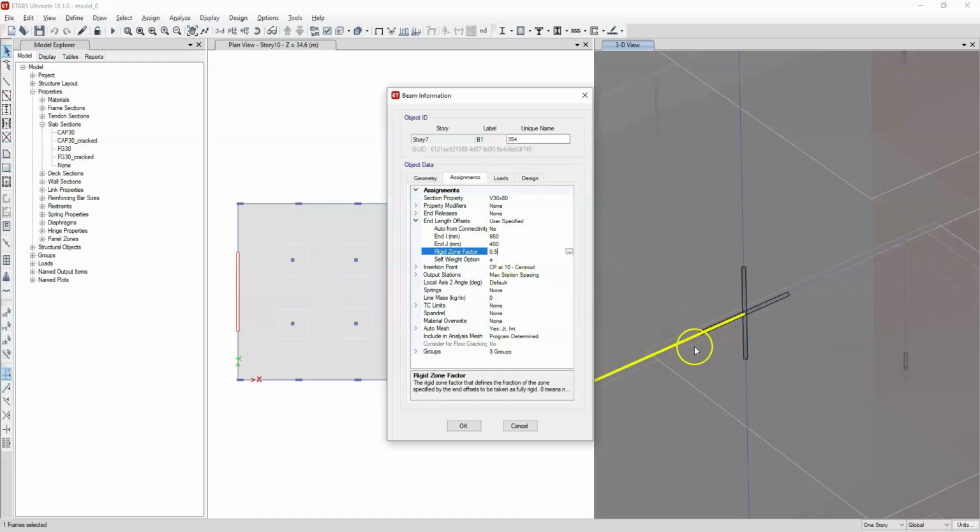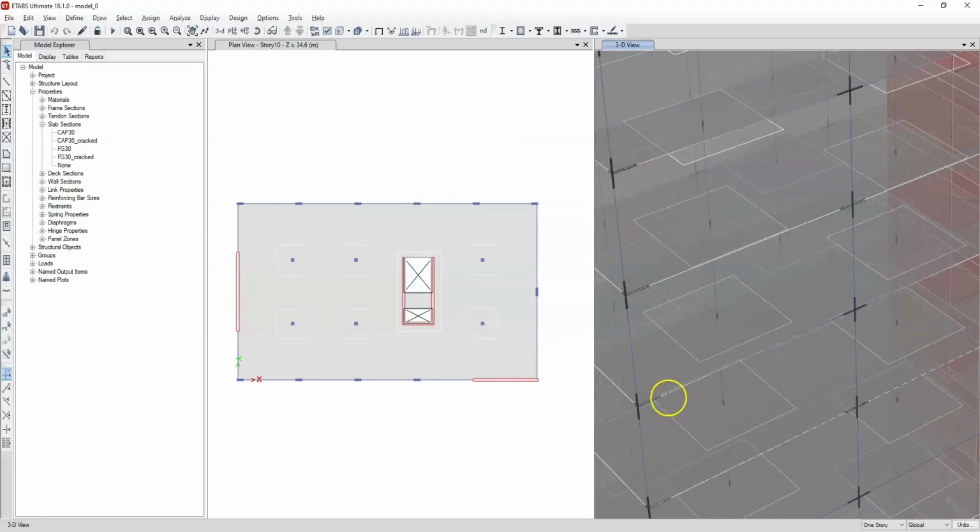This precision is used because there are important aspects related to the building's stiffness. Since we are performing checks like interstory drifts, it is important to quantify these values as realistically or reasonably as possible. For example, when dealing with relative displacements between floors, it is also important to quantify the stiffness of the elements in our frames as realistically as possible.